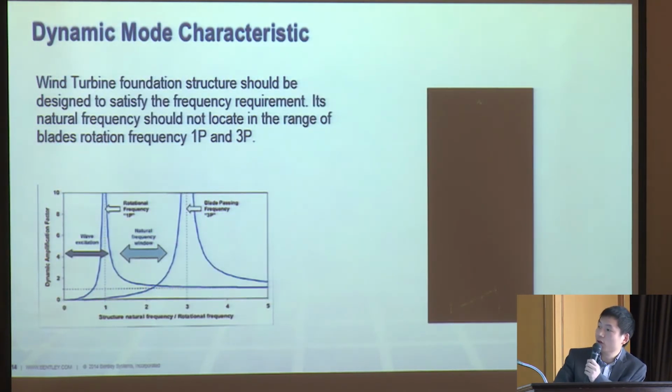Sometimes, for example, for an offshore wind turbine foundation, you need to check the dynamic mode shapes of the structure. And SACS can perform a dynamic response analysis to extract the mode shape. And the wind turbine foundation structure should be designed to satisfy the frequency requirement.